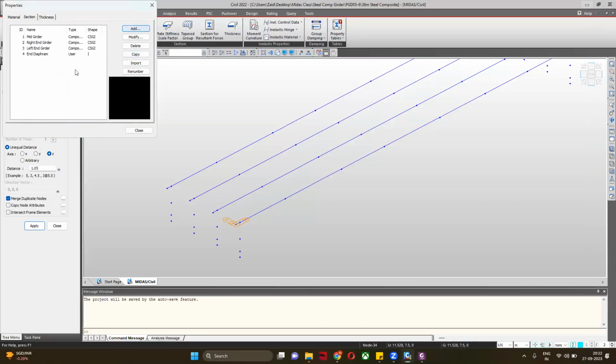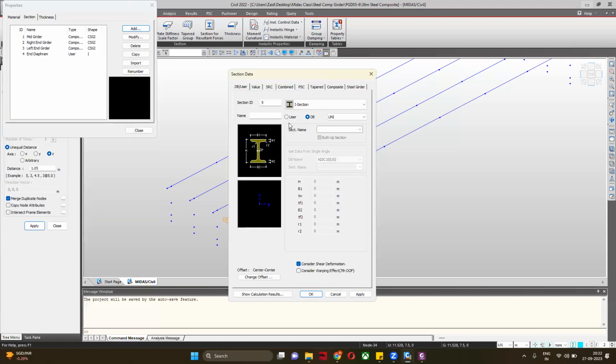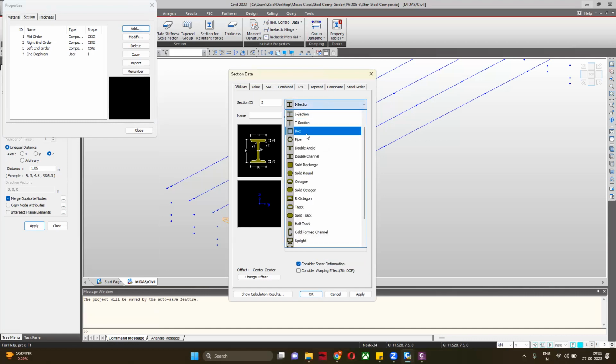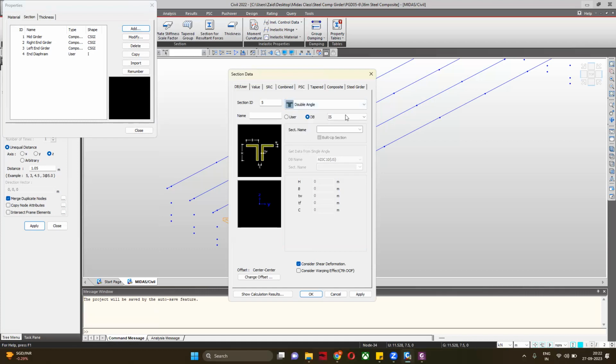So we'll go here. Now here we can use our standard angle. If we go, first of all, Indian code, let me see if the double angle is okay. It is showing everything. The double angle we required is not coming, so user define.